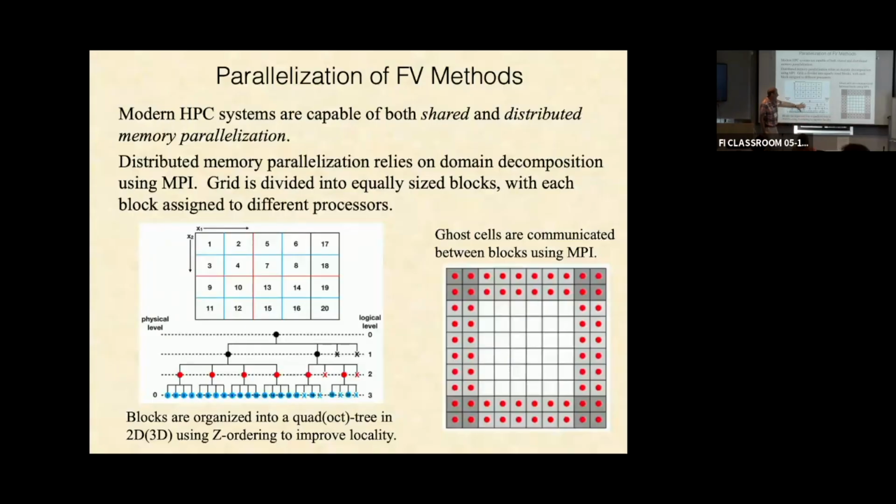So again, this is a data structure in Octree, which would just be represented by a class representing a node in the tree, which has a pointer to all its 4 or 8 leaves. That pointer would then just point to instantiations of that same class, which would then be the next level of that node. And you store things like the ID and your level in each of these class elements. It's not related with the refinements, right?